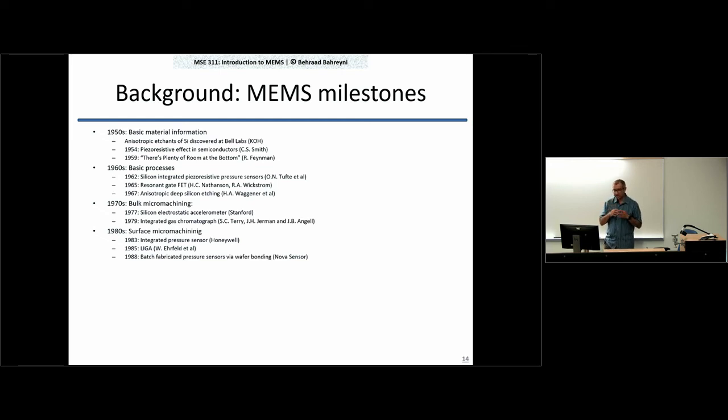And then in the 80s, they went beyond the limitations that were imposed onto them by using microelectronics materials. In microelectronics, we use essentially silicon and aluminum only, right? And maybe a little bit of a dielectric here and there to isolate the different stuff from each other. In MEMS, we needed more, right? So they looked at surface micromachining, depositing whatever material that you need on the surface and removing the portions that you didn't want, as an alternative technology. New demands and therefore new solutions.